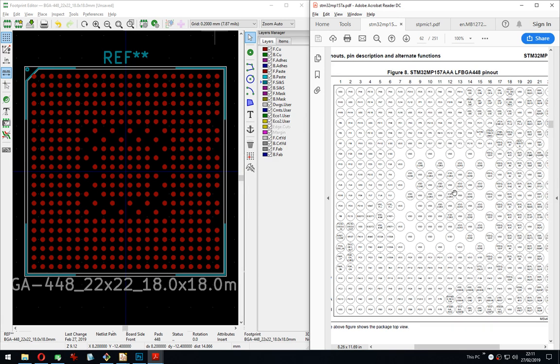Yeah, it depends on the chip vendor, because there is usually a bootloader before U-boot, and it varies. There's no standard way really to do it. On these STMs there is in the ROM, so it just boots U-boot, but for the SAM there is this bootstrap thingy. Okay, that was in the chat. Sorry, I did not see what you were asking.